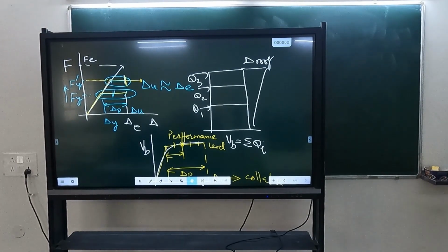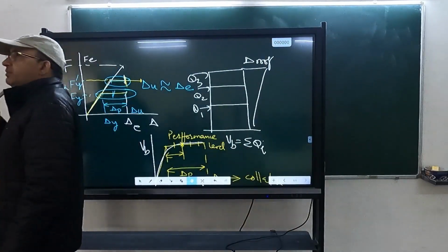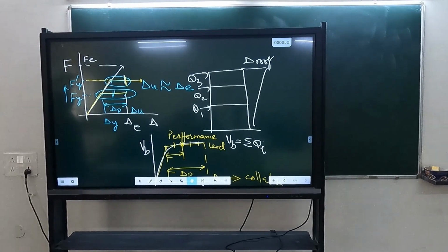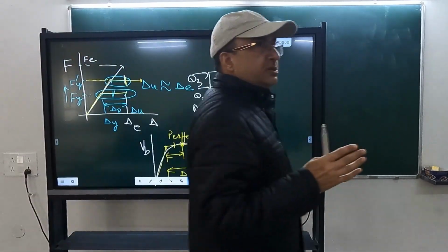Okay. So as far as the structural components are concerned, the design procedure remains the same. You have to estimate how much to increase the strength. The only difference is that previously you did not know how much increase is enough. Now you will be able to estimate that to achieve this particular performance level, you need this much increase. That's why we call it performance level. Strength, we are deciding with respect to the performance. We can relate the strength required with the performance objective we are targeting. That's the difference between the two methods.